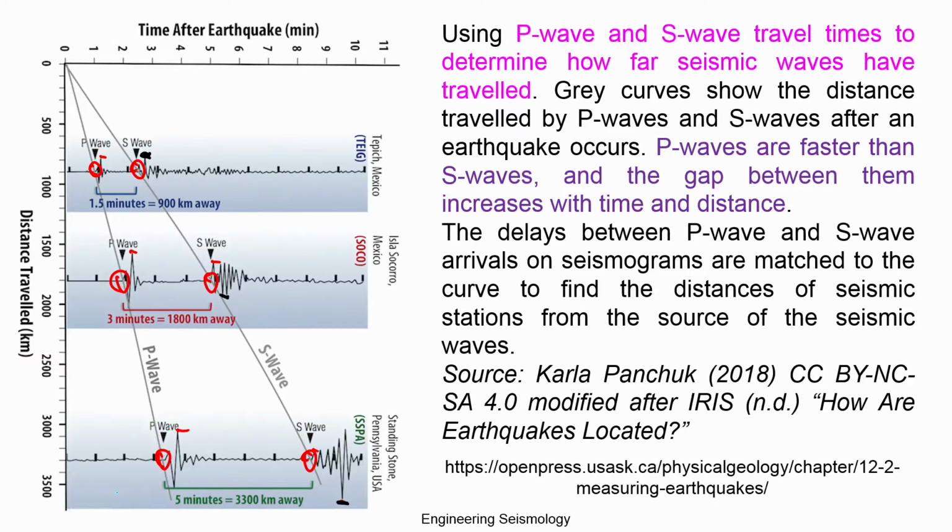So, you can see here, this is repeated up to this, here it is repeated slightly larger, and here it is repeated up to this. So, that is your duration, and the amplitude keeps increasing with the distance. That is one observation we can make from here. And then the gap between the P and S wave arrival time, here 1.5 minutes, 3 minutes and 5 minutes, this time also keeps increasing. So, these details are useful to show where exactly the origin of the earthquake is located.